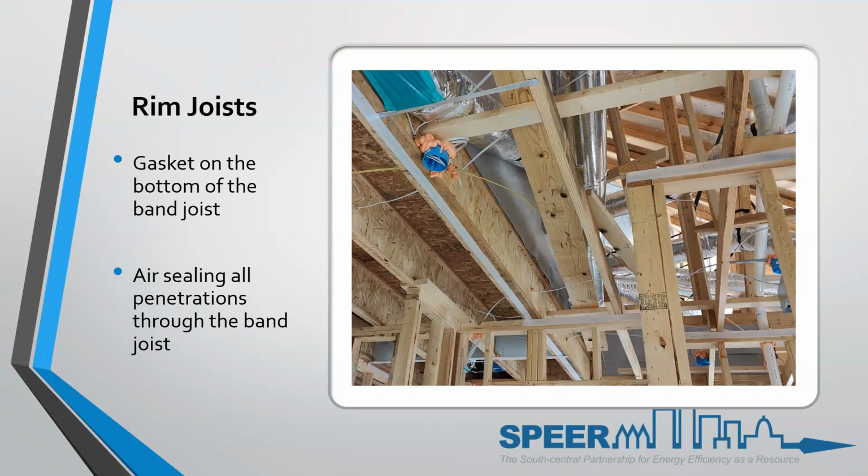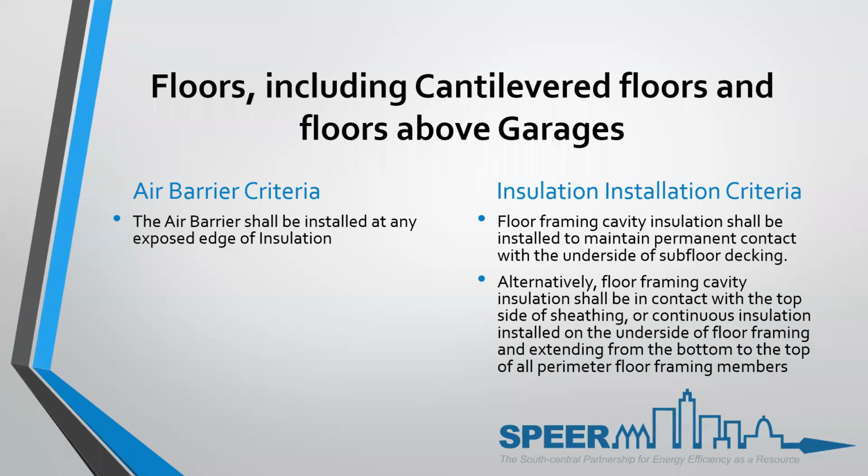But here we see there's a long 2x8 and then there's a 2x4 or 2x6 up in there, just laying down on the ceiling joists, and those should be removed. Otherwise, when the attic insulation is being blown, if he's too far away from that, it's going to leave a void of insulation directly below that 2x8. Yeah, some of it may fall in and fill that gap over time, but that just means now you have in those areas less insulation depth than what you need because the pocket was left below that piece of trash that was there.